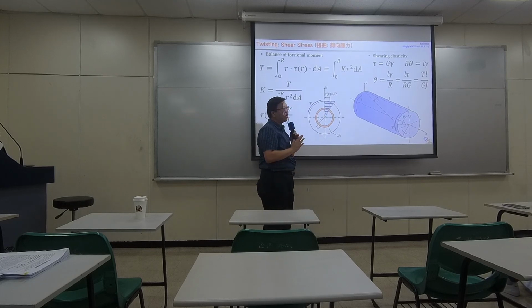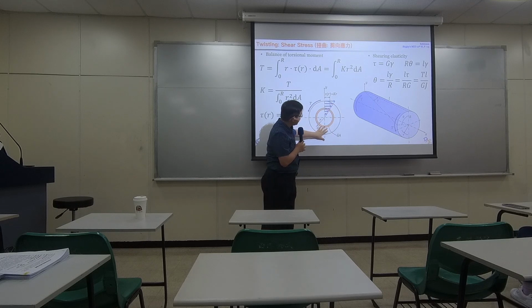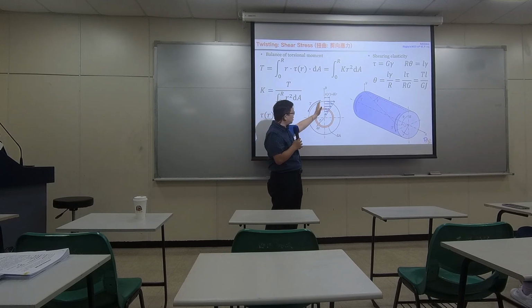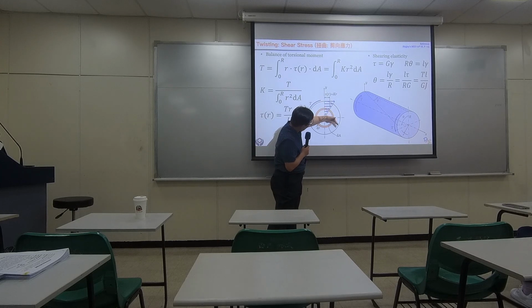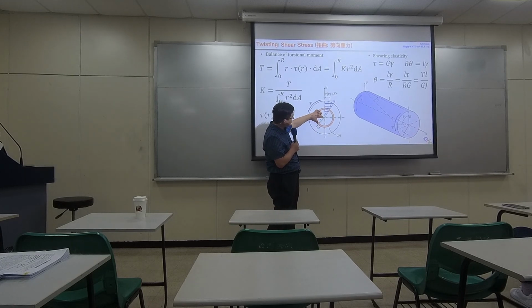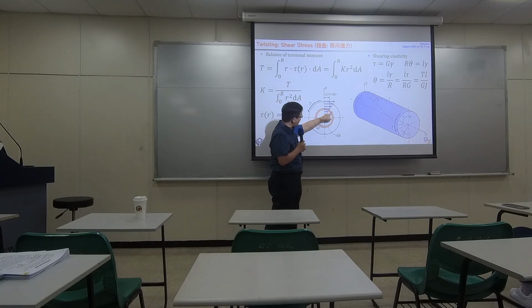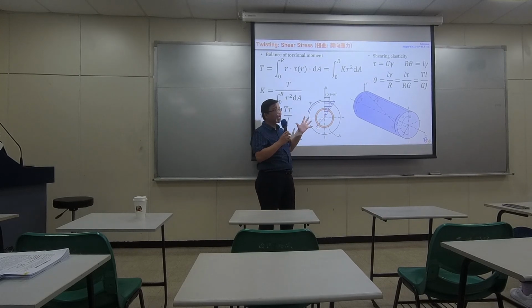The reason why is because all the forces applied inside the entire cylinder are exactly the same. You can say it's axially symmetrical. So it's the same everywhere. Whatever you compute right here is exactly the same everywhere, as long as the radius is the same. So why don't we compute the entire ring at the same time?